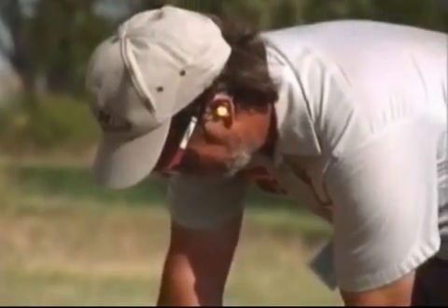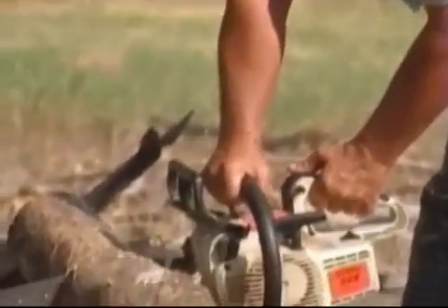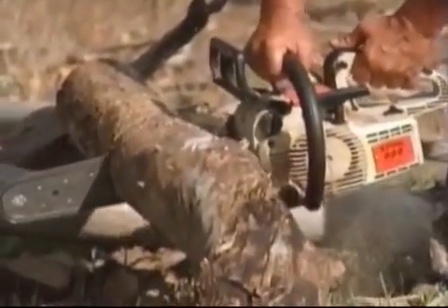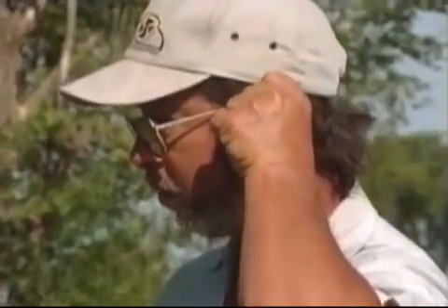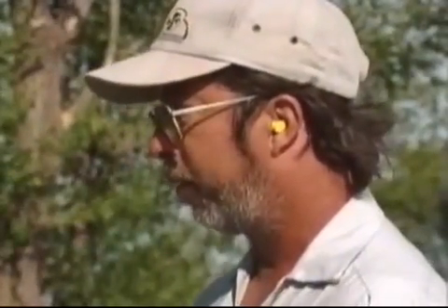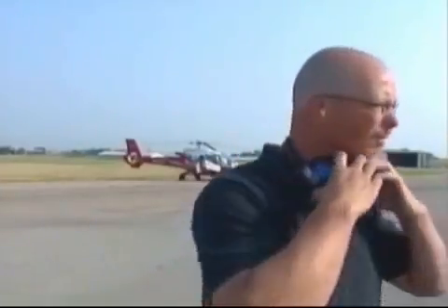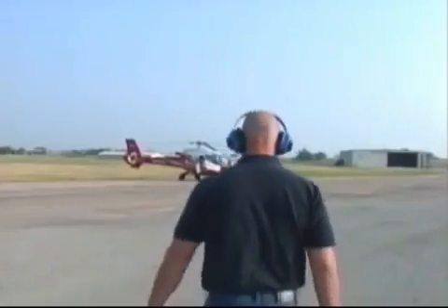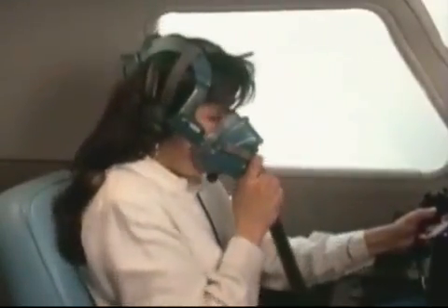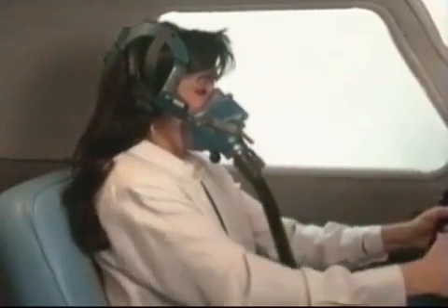This earplug type provides protection of 30 to 35 decibels of noise across all frequency bands. The earplug is rolled between the forefinger and thumb and inserted into the ear. It should be held in place for approximately 20 seconds or until it has fully expanded. Earmuffs and communication headsets are other hearing protection devices that are readily available and in some circumstances more convenient than earplugs. It is important to realize, however, that these devices can interfere with the use of oxygen equipment.